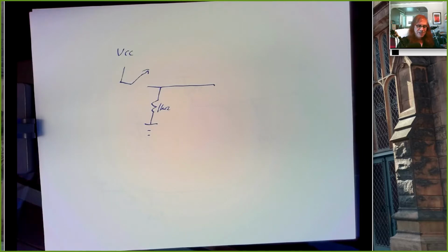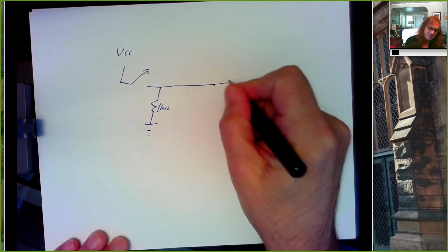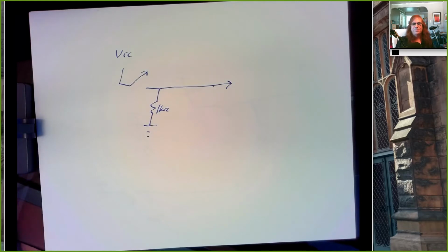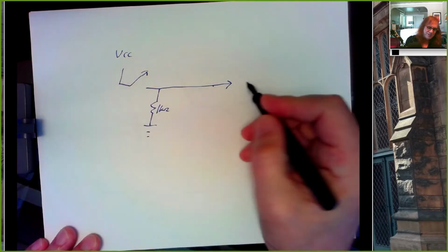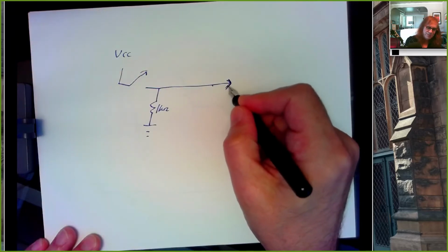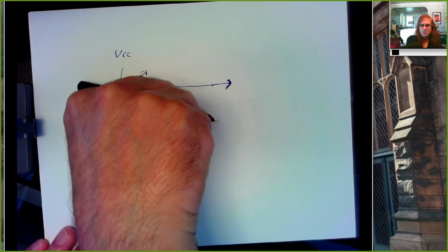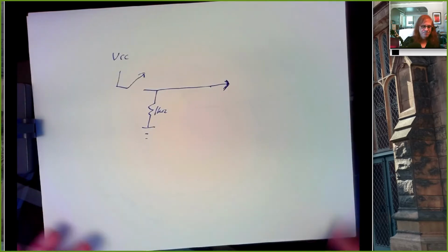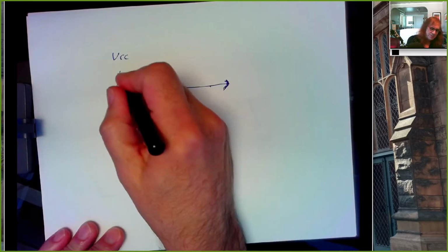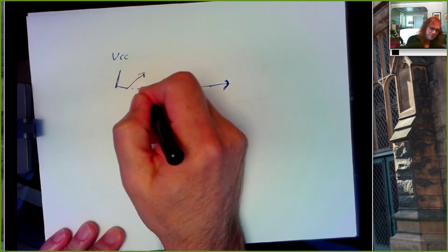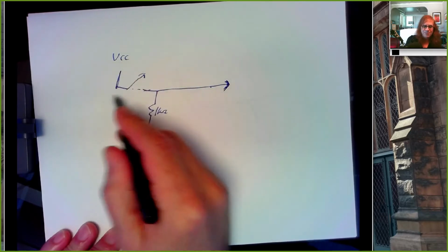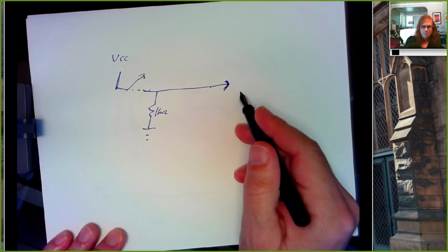But there are a lot of circuits where, if I feed this to the input, the chip will fail. In particular, there are some very expensive microprocessors that might cost you $50. If you take this circuit and hook it up to an input pin and close this switch, that input pin will fry, because closing this switch allows, theoretically, unlimited current to flow from 5 volts into that pin.